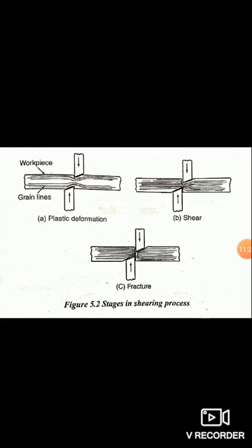We told that burrs are formed. To reduce the presence of burrs, it is important that the blades are sharp. Also, it is important that they do not deflect under pressure, and that they are not set too far apart. An offset of the blades is needed for reducing the production of burrs. Okay, thank you.